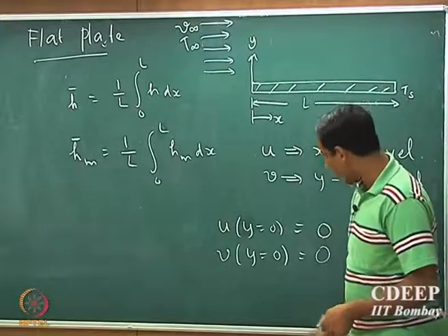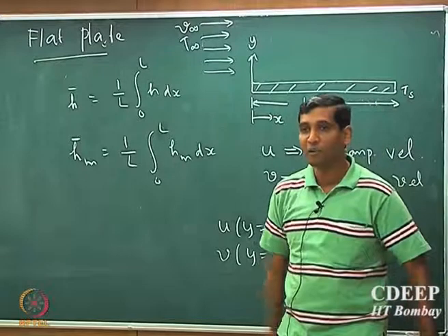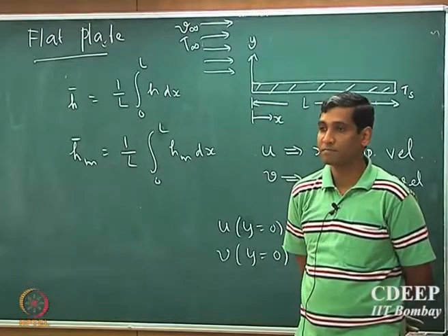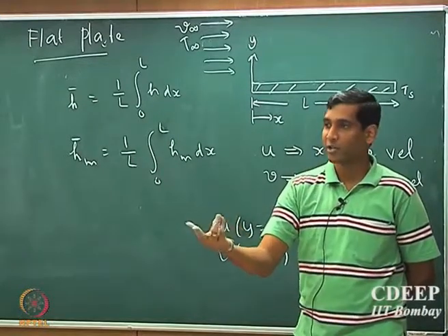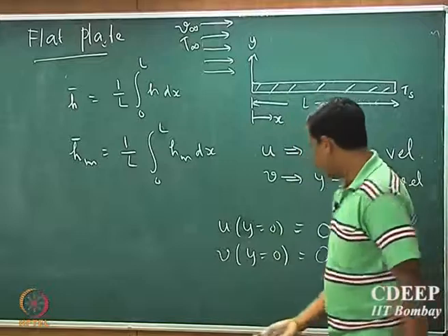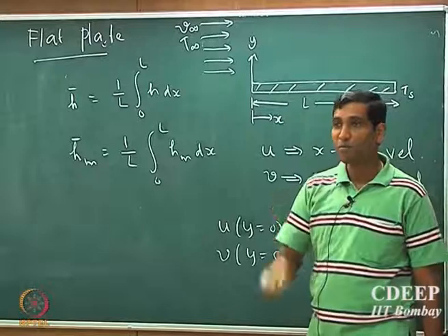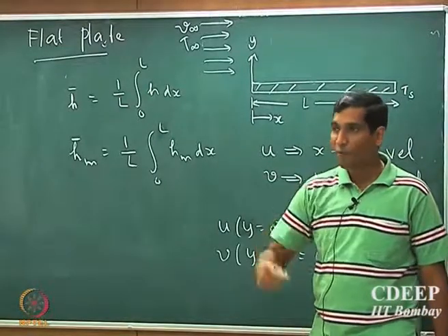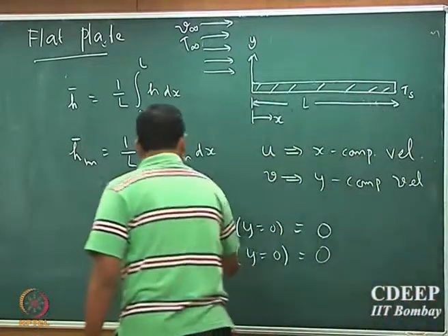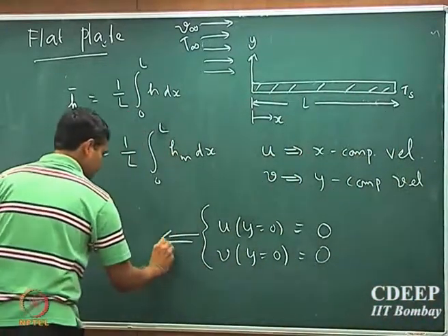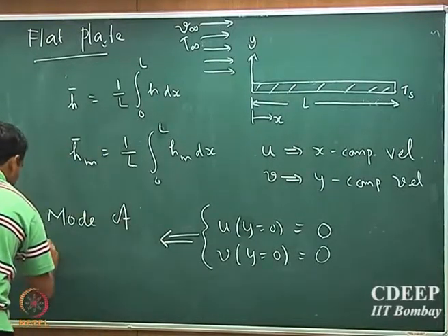So that has an important implication in heat and mass transport. What's the mechanism of heat transport at the boundary? What's the mode of heat transport? We said there are 3 modes, right? Conduction, convection and radiation. Because the velocity is 0 at the interface, the actual mode of heat transport from one phase to another is actually conduction.